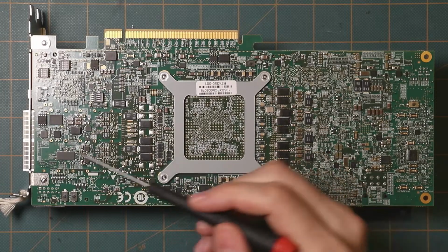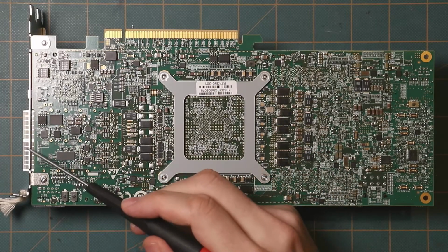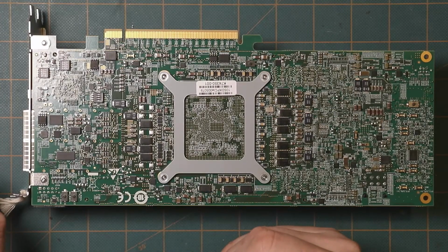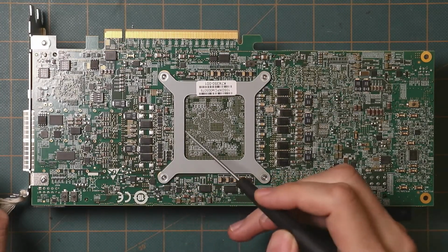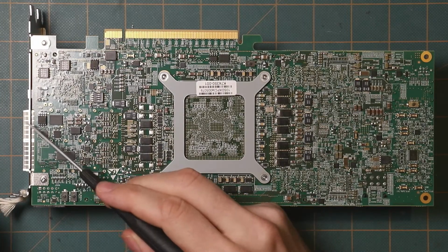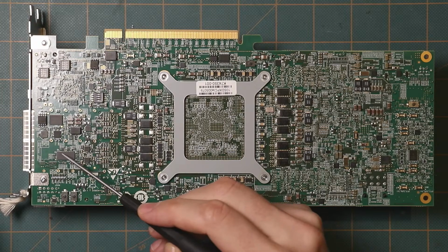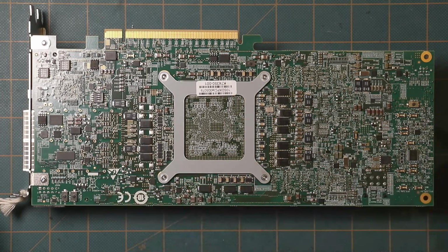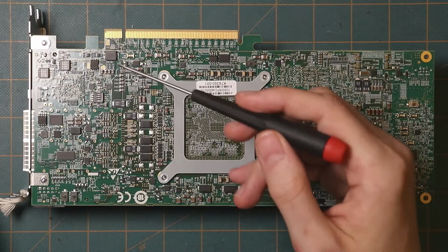This chip over here is kind of supporting circuitry for the QSFPs. Let's see, what does this one do? It sits on the I2C bus from the FPGA, and it basically does level translation, and it has, I guess, LED drivers in it and drivers for the low-speed control pins on these modules. So that's what that does.